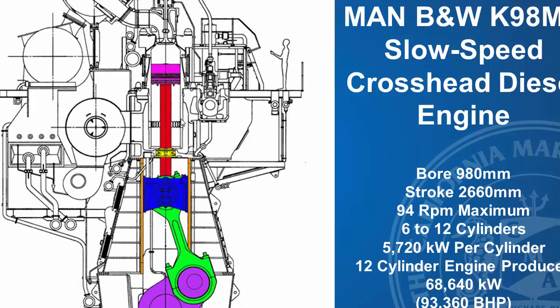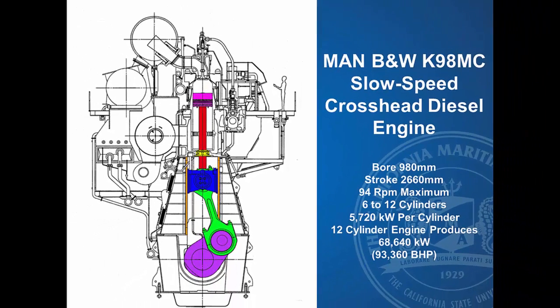They have actually two injectors, so each pump has two high pressure pipes coming off of it. But in relation to the size of the pump, the high pressure pipes are quite short. The Burmeister-Wain is the only separate pump and injector system that I've seen that does not have a delivery valve.